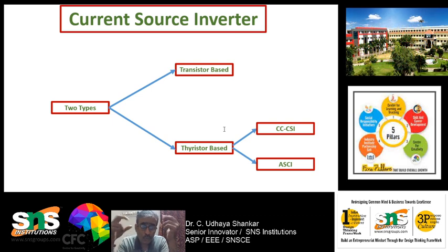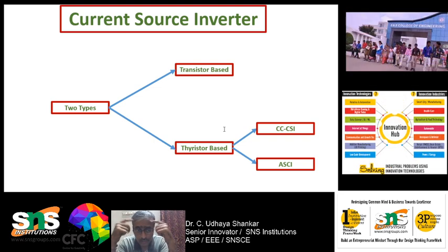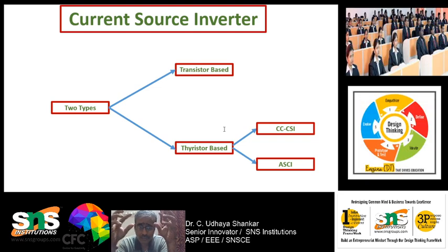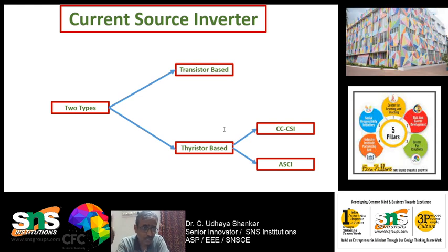Whereas the output current changes with respect to load in a voltage source inverter. In voltage source inverters, a large capacitor is used in parallel at the input DC side. As I've said, there are some drawbacks when we use the voltage source inverter in high power ranges.